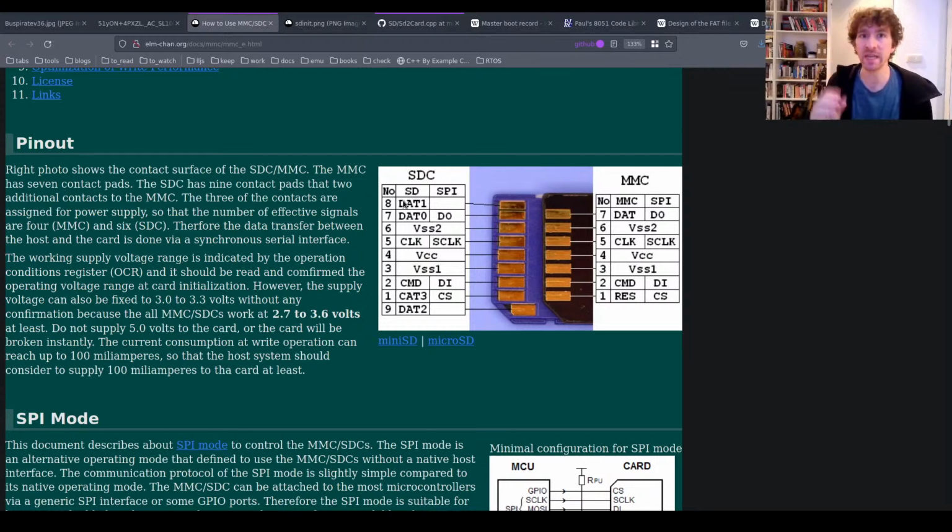There is an amazing talk online by Bunnie Huang where he bought hundreds of different kinds of SD cards and cracked them open, and found all these different microcontrollers inside them, because the microcontroller controls where it's going to store the bytes and how it does wear leveling, which is a concept in flash memory itself.